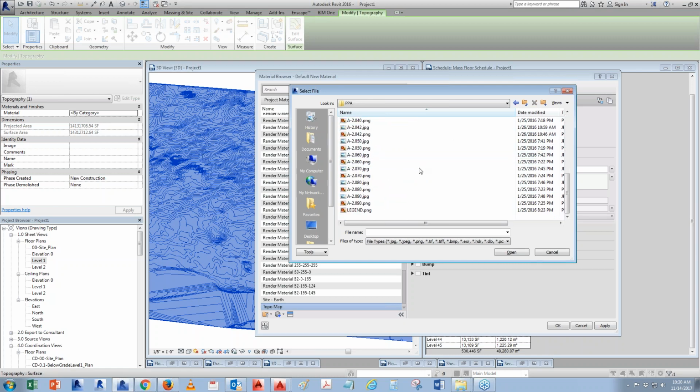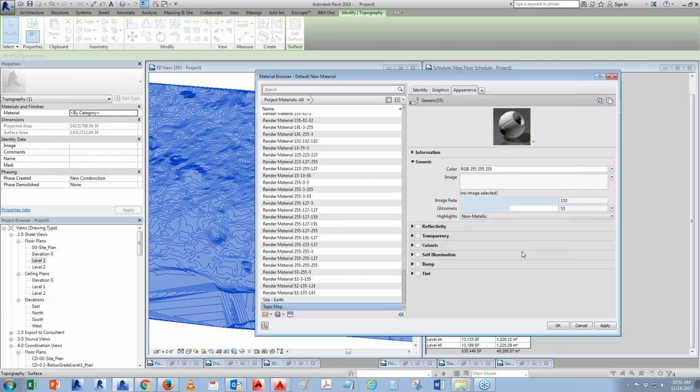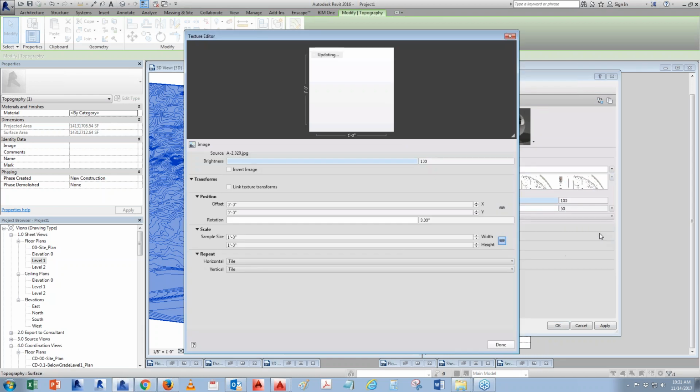Let's see. Thumbnail. Okay, let's assume that that is your topo map, and you want to put it into your sitemap. So I just put it in there and edit the image. The one thing you want to do is calculate how big your square footage area is. Most of the time, for the images, it's going to tile it, one by one. So what I typically like to do is put in 200 feet, so that you know you're covering within that range.